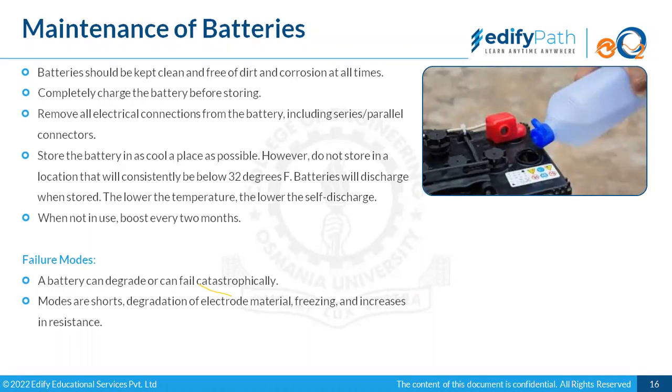So if you keep your battery unattended for a prolonged, very long time, due to self discharging it could go below the lower end voltage and go into deep discharge. At that time, it won't be ready to use. You might face issues where it won't start charging through your normal charger, and you have to do something to lift the voltage to the lower end voltage. You have to lift it, and then you can plug in the normal charger so that the charging can start.